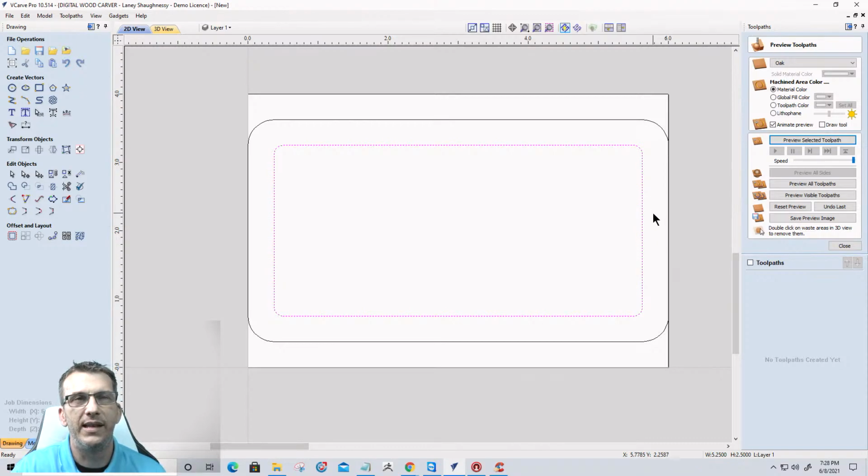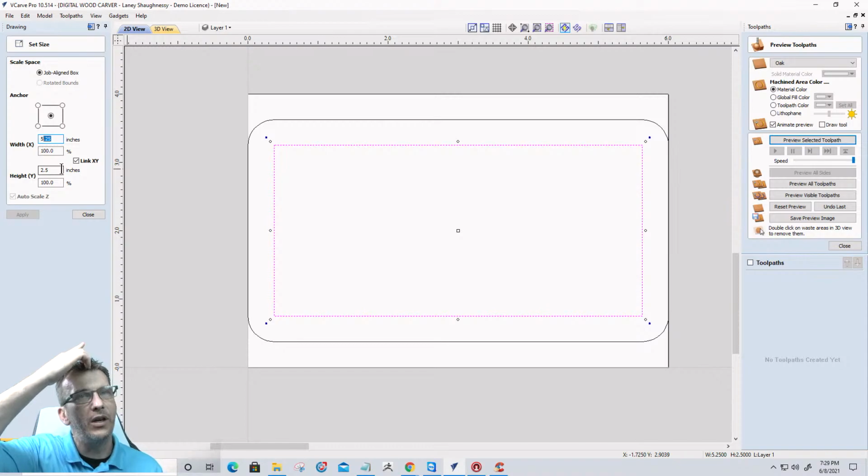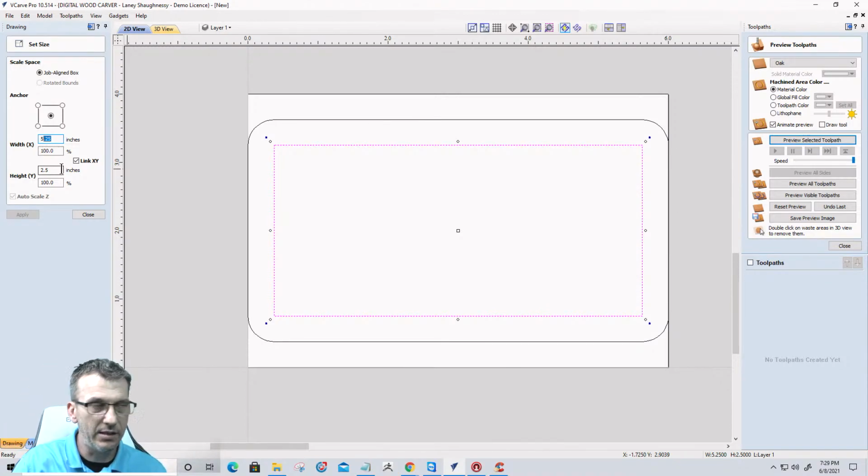We'll get the size of that in a minute. But on the ends, I would like it a little bit wider than that 3/8 of an inch. So I'm going to undo my 4 corners and get this sized down. Let's do this properly. Let's go to the size tool, and on the width, I'll give myself an extra 1/8 of an inch on each end, so I'm going to go with an opening of 5 inches because it's at 5 1/4 right now.